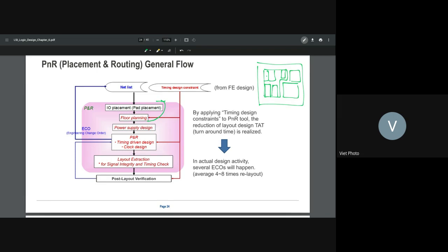There's none until now. There's a lot of research on macro placement, but nothing's working because it depends on a lot of timing, especially critical timing. After you place it, you have to run placement, and then go down the flow until routing to see what the timing is. If everything is correct, this cycle takes at least about 1 week.